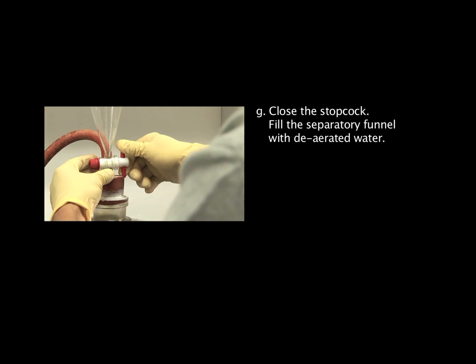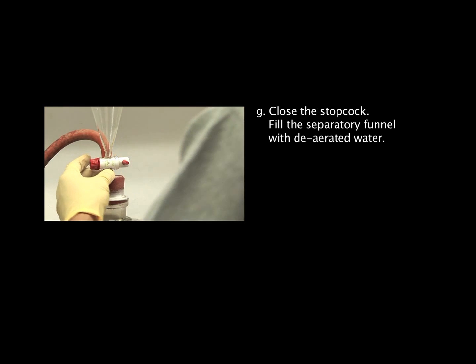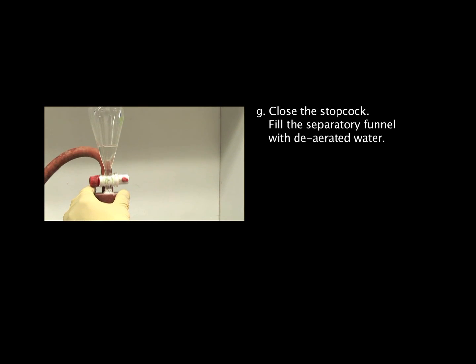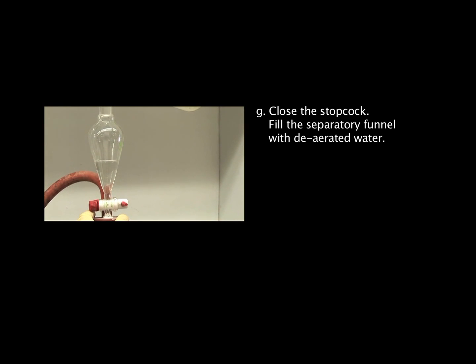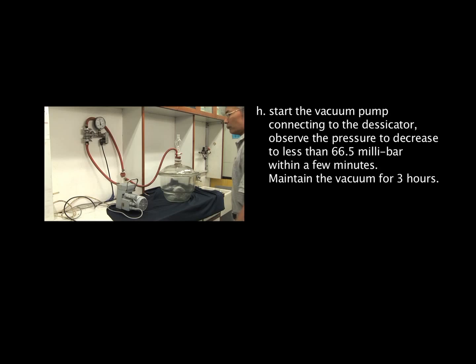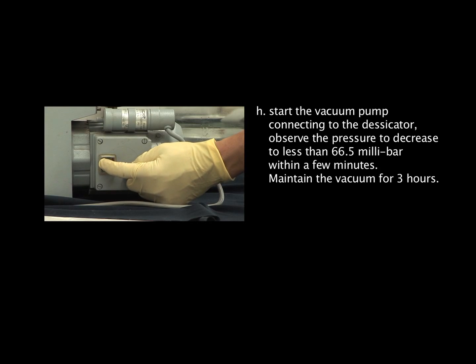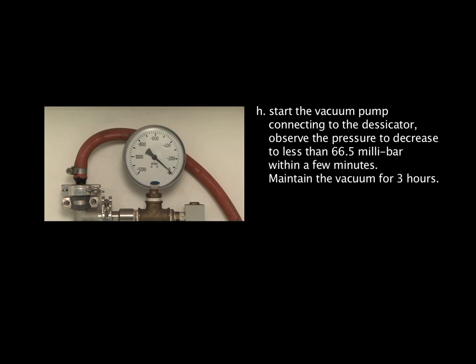G. Close the stopcock. Fill the separatory funnel with deaerated water. H. Start the vacuum pump connecting to the desiccator. Observe the pressure decrease to less than 66.5 millibar within a few minutes. Maintain the vacuum for 3 hours.